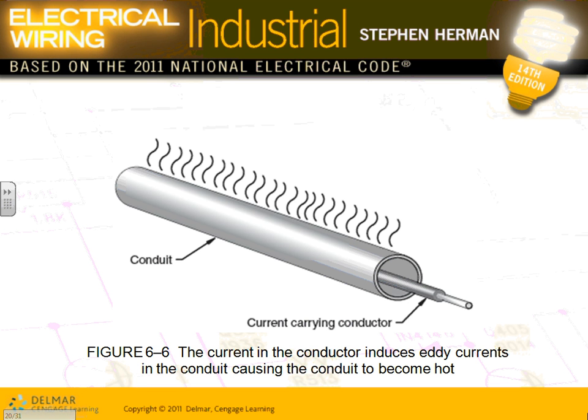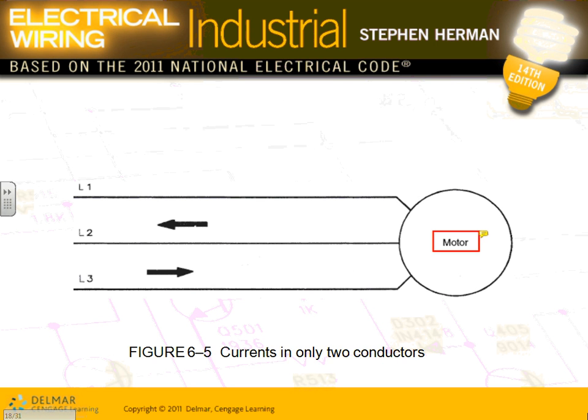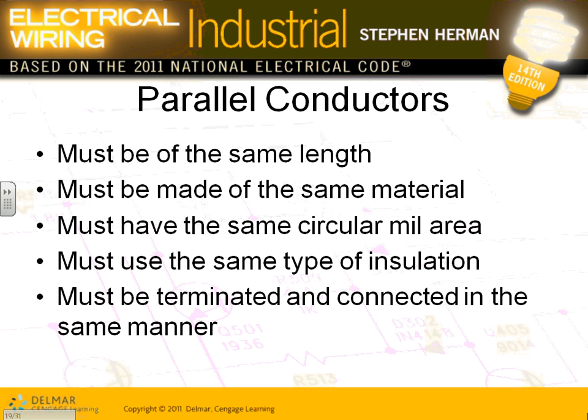In close proximity. The voltage drop thing, if you're building a system within a machine, for example, do they use the voltage drop, where the NEC rules don't exactly? UL also, engineers of UL take consideration for voltage drop. Yeah. Absolutely. You come up with these ridiculous numbers. Let's just say you're only going to go 6 inches. Yeah, but they use the amps, the continuous load. You use the formulas, and you choose the largest one.